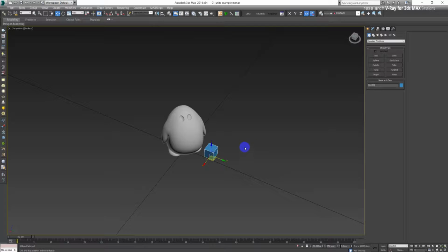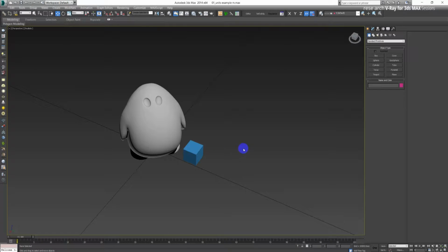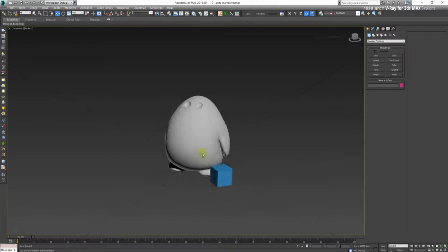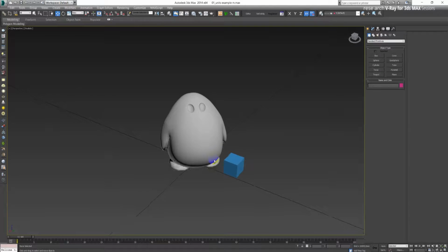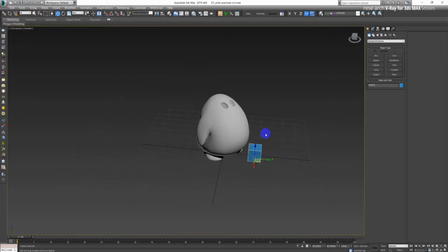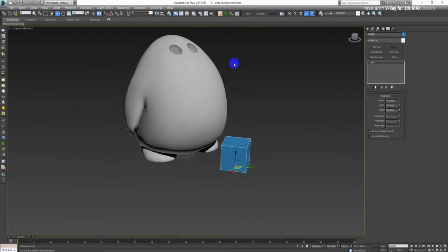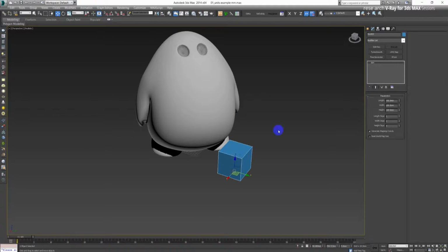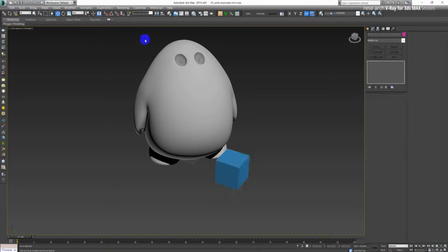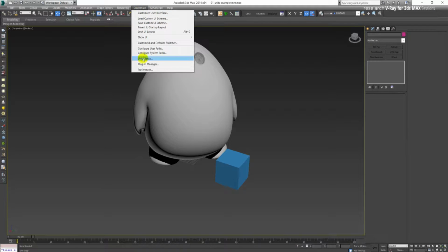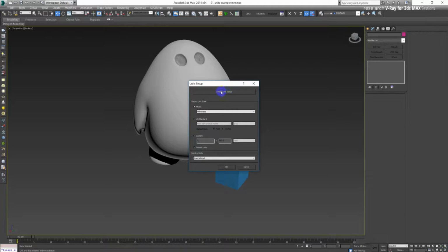And one more thing that I want to show you, and that's going to be all, and I believe that there cannot be any other misunderstanding about the units, is one last setting that is quite important. I will leave my millimeter scene open, and there's this tiny setting that goes quite unnoticed. In the system unit setup, you have this Respect System Units in Files.